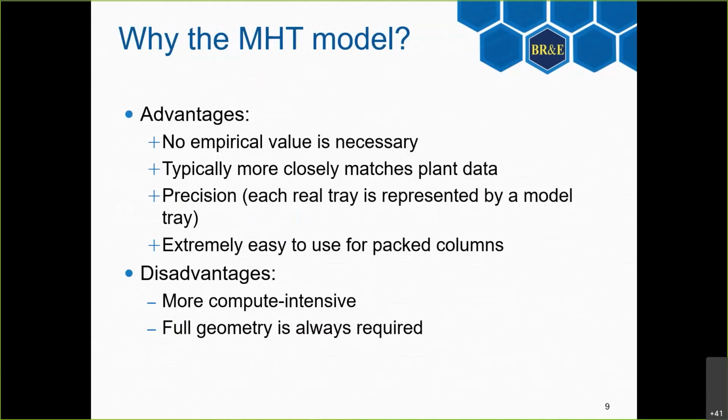Another point is the agreement between reality and model. We incorporated the mass and heat transfer model into ProMax in 2016, I think. It was actually before I started with BRE. And from our experience, it really does a better job when it comes to matching plant data. Of course, we were hesitant in using this novel model at first, but from what we've seen, it really is a better way to get closer to plant data when you're modeling an operating plant.